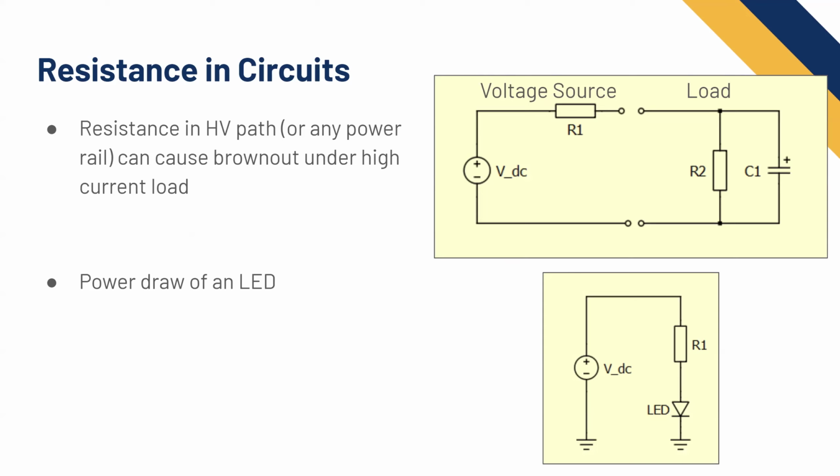This circuit here is showing, on the left, what a real voltage source looks like. There's going to be some resistance inside of that voltage source because it's real components, real metals, and they have some resistance. This is the simplest way to model a battery. You could also add some more RC components that are time dependent. So you could do a resistor, capacitor, as many of those as you wanted, and then it goes out.